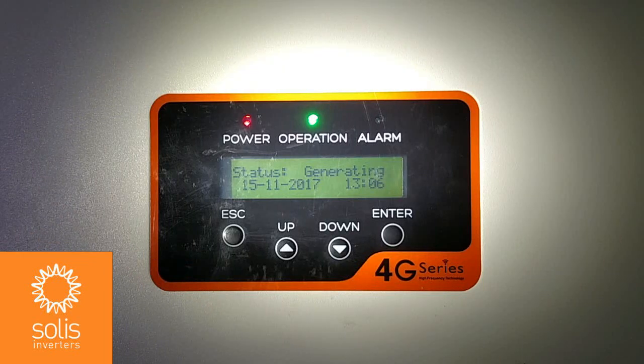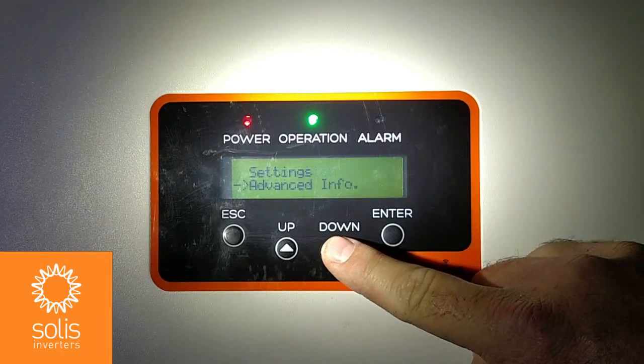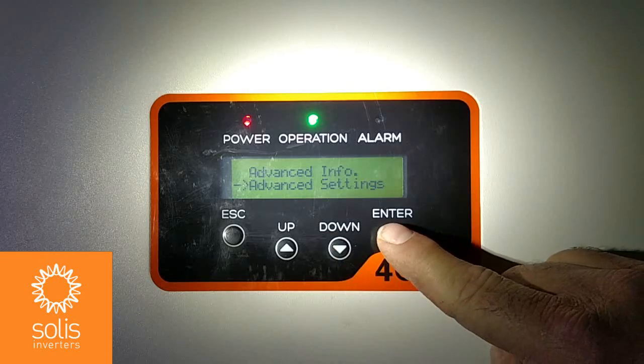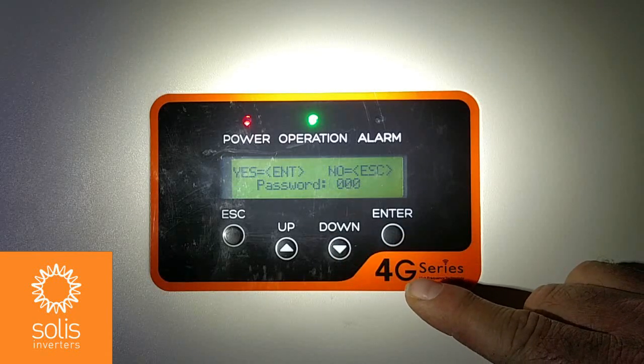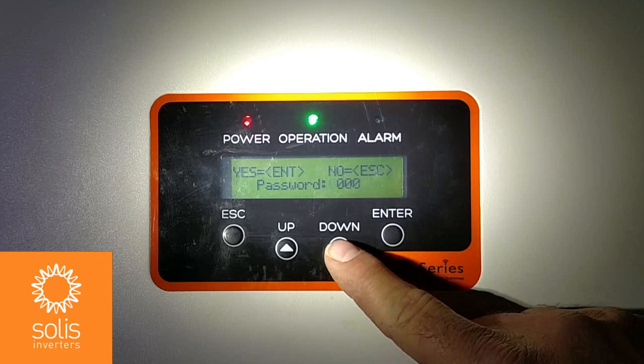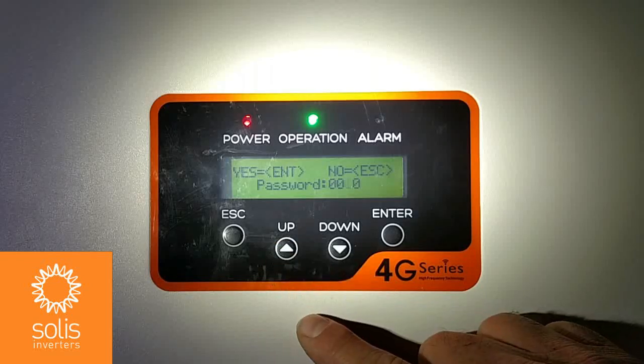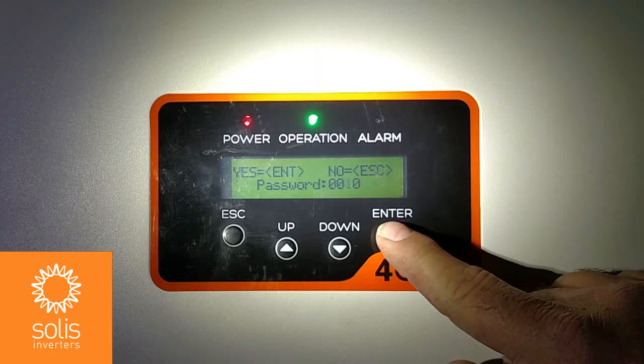Okay, to start the process of changing the grid standard, we will use the menu to turn the grid off, and then we will change the standard and turn the grid back on again using the buttons and submenu. To get into the menu, you can always press enter, and that'll give you the 4 submenus, and you can scroll down using the down button to advanced settings and enter this menu. This is where we will do our work. Now, the password for advanced technicians is 0010, so you can use your down arrow key to move the cursor over to that third position, change it using the up arrow key to a 1, and then press enter.